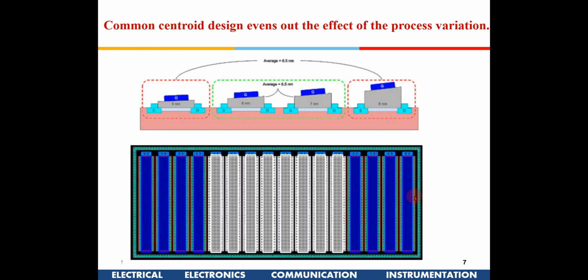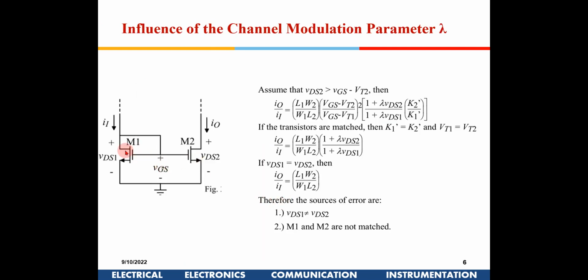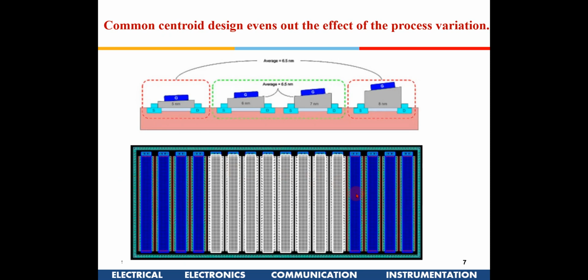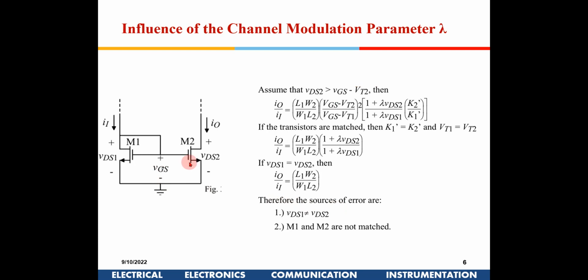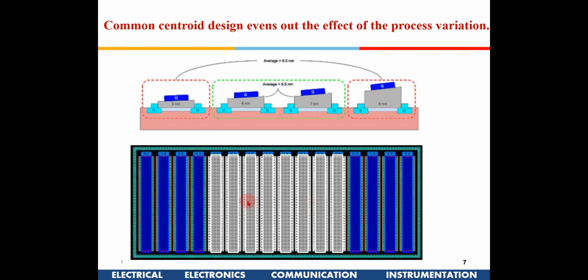So to avoid mismatches, we said we can use this kind of layout, where this transistor M1 is split and M2 is spread on both sides. Here, this is multi-finger, which we discussed in the morning. Even if M1 is one transistor, generally we keep W by L very, very large. For a given current, if W by L is very large, I can keep VOV less, isn't it?